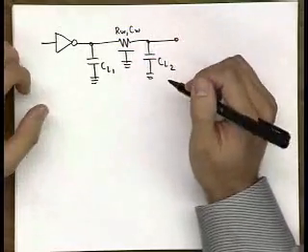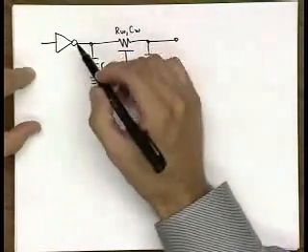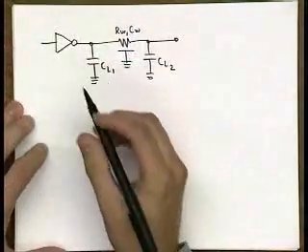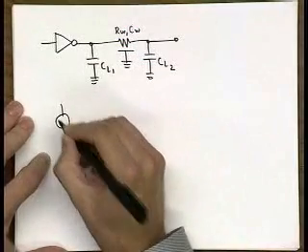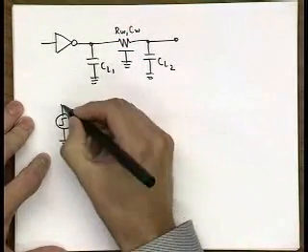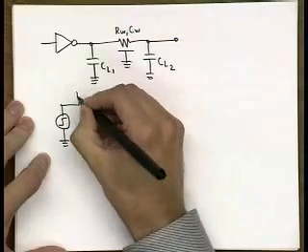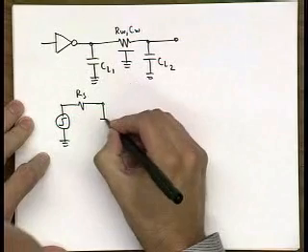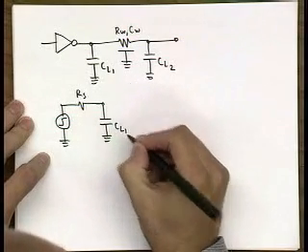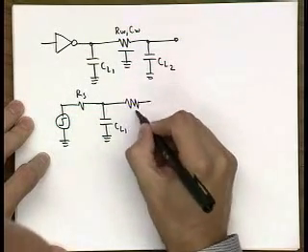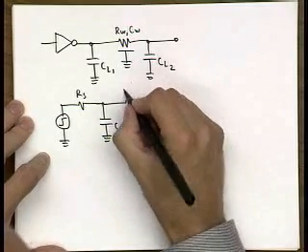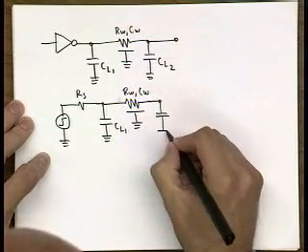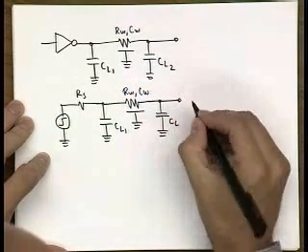So let's try to calculate the propagation delay of this particular structure when you apply, again, a step input. So the equivalent model for that analysis would be this. You have a step input, then you have the equivalent resistance of the source of the driver, and then you have this capacitance CL1, then you have RC due to the wire, and we have load capacitance at the output.